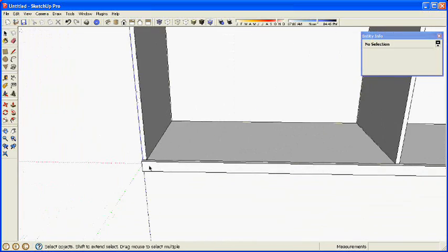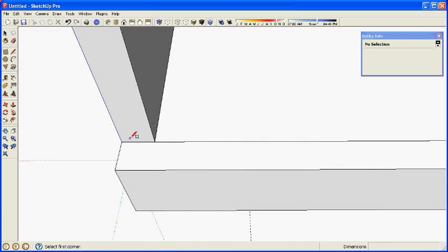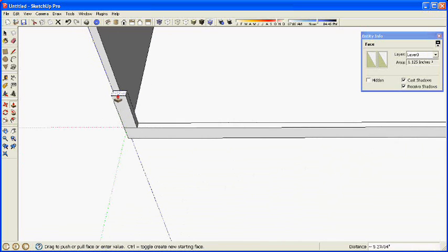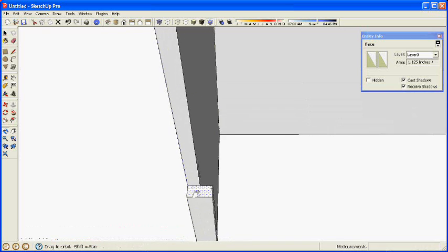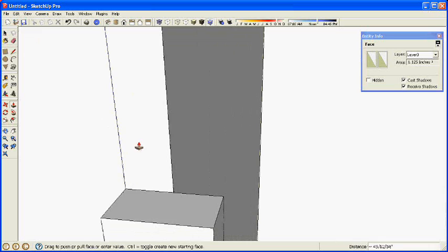Alright, so now come back over on this corner, and I'm going to draw a rectangle for the section or the end of the face frame style. We'll type the dimensions. When you're dragging out the rectangle, drag it out distinctly longer in one direction than the other, and that will help you see which number you have to enter first.